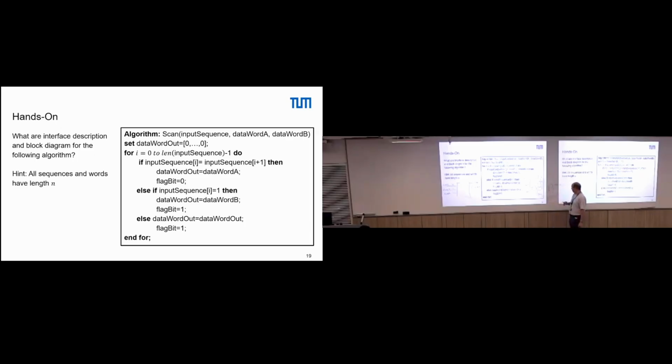I need to think of how to realize all other cases. Most likely we need another gate here in between. Probably it's simpler. Sorry, we remove that and just put this here, right? Because in all cases where this is not set, an inverter is needed. So in all cases where this bit is not set, the flag bit is set, right? And if this is true, then the flag bit is not set. So it's just inverted and put to the output.